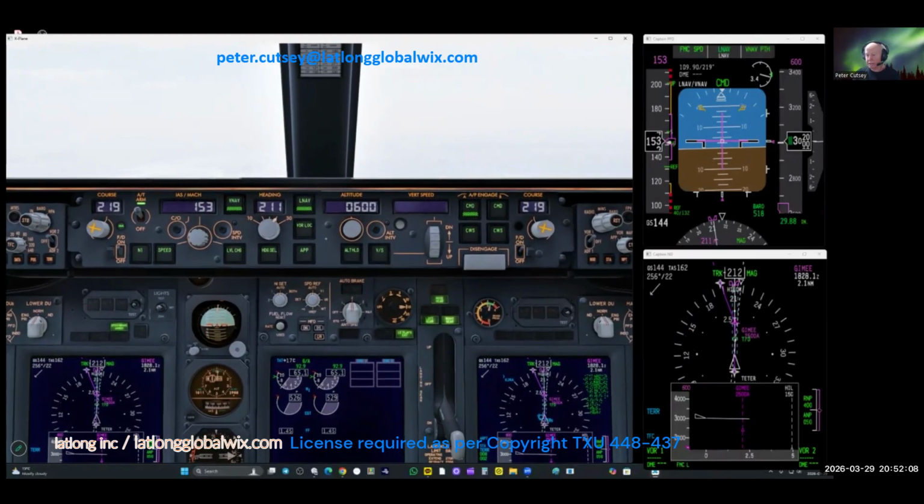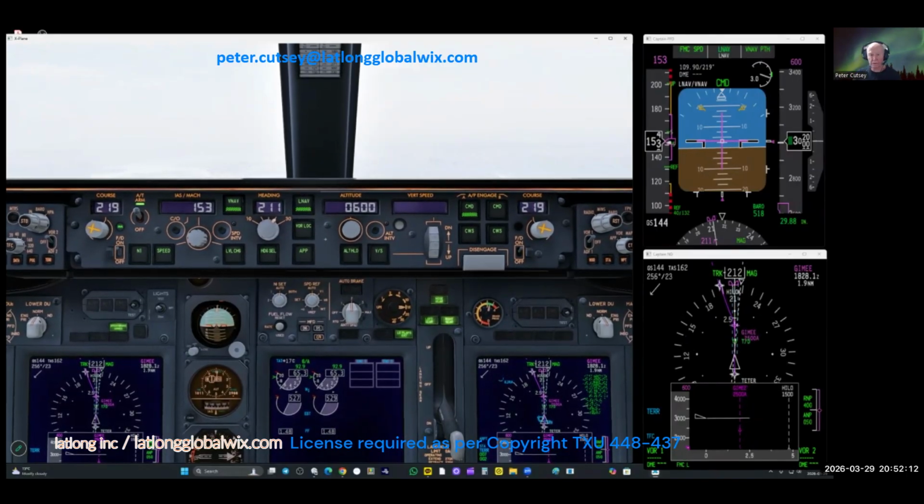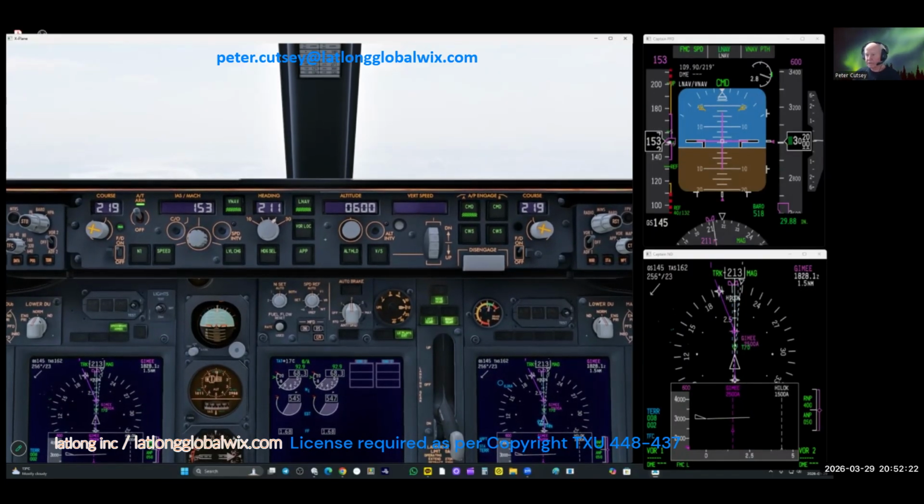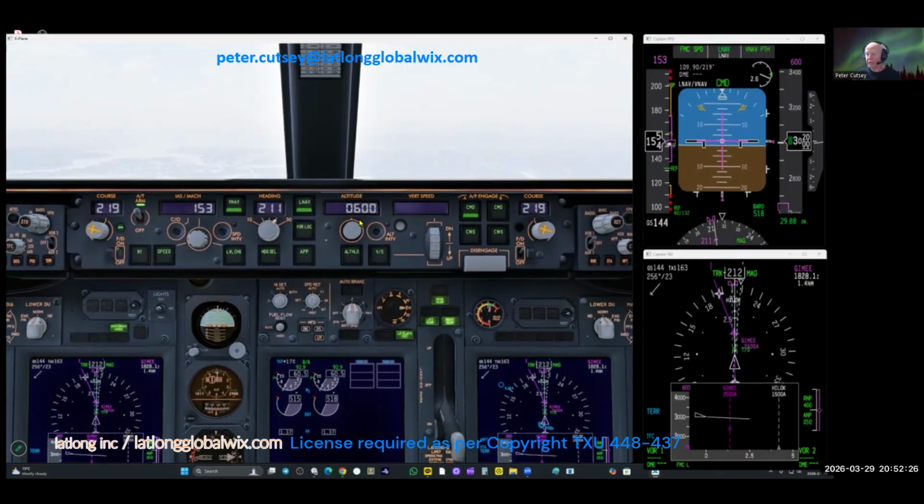Top of descent in 1.25 miles. Follow your company SOPs on what to set for minimums. We set 518 on the barrel and we set 600 here on the MCP.